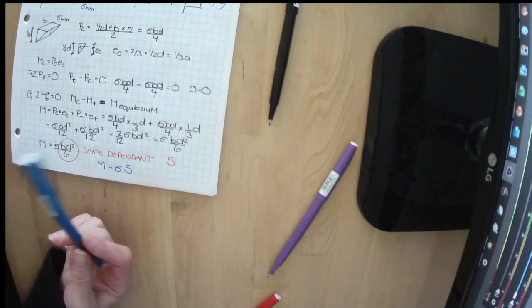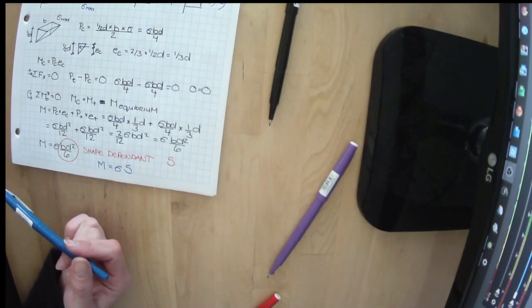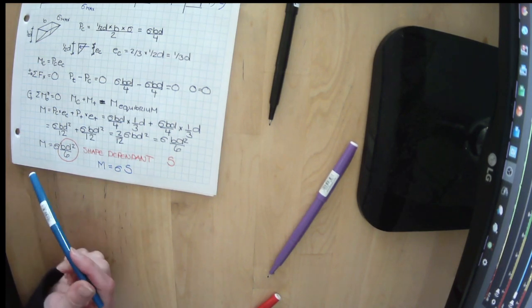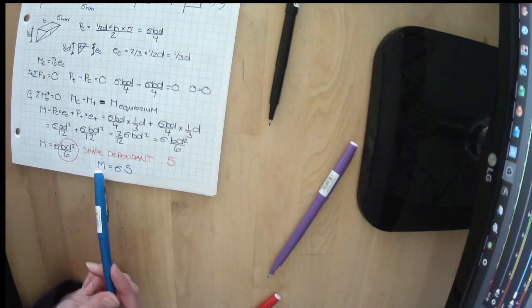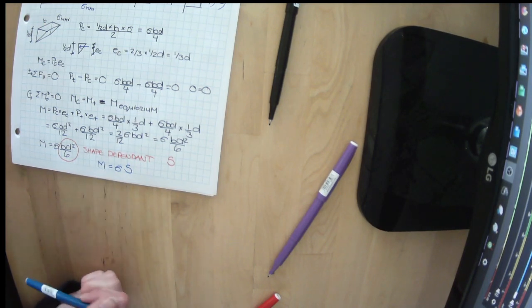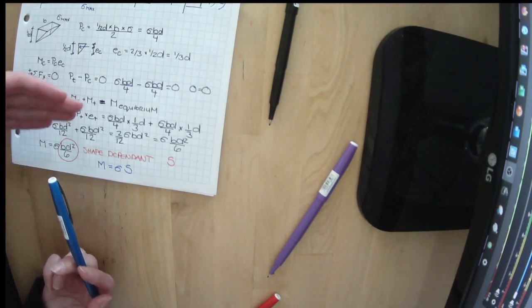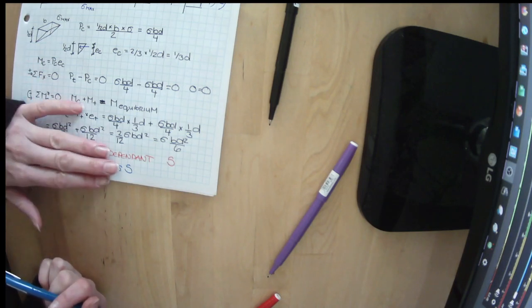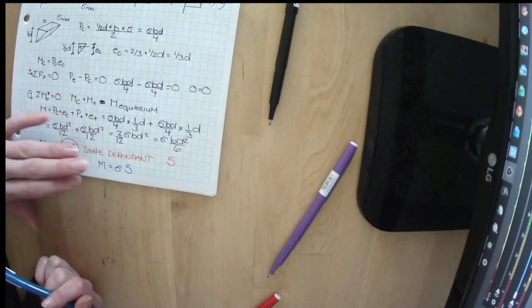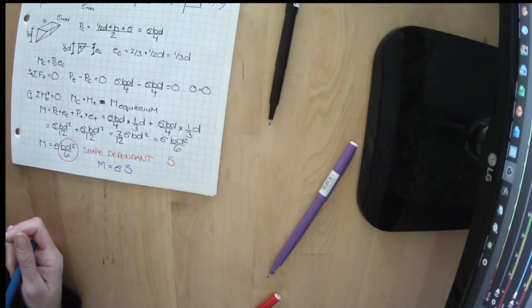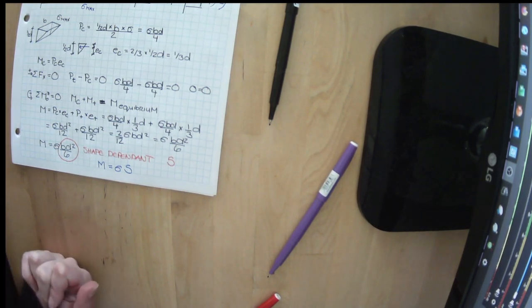Now, if you guys remember last term, we were able to figure out what the actual moment on an object was. So if we know what the actual moment is, and we can figure out what the maximum moment can be on that particular shape, well then we should be able to say if that particular shape's maximum moment is greater than the moment that's applied to it, then our member should work.